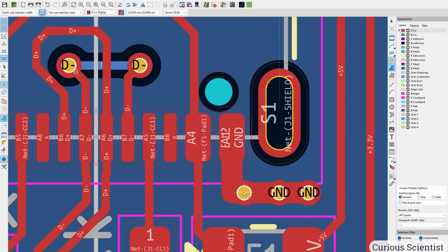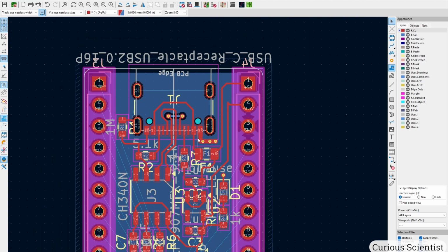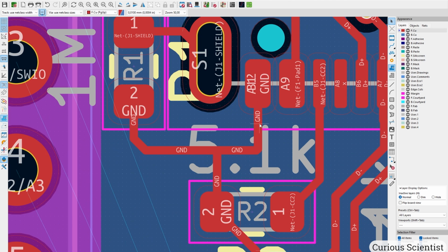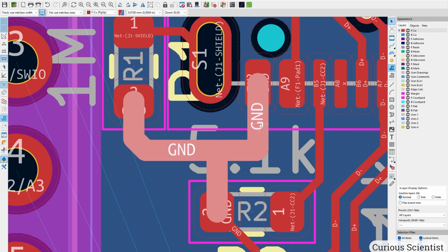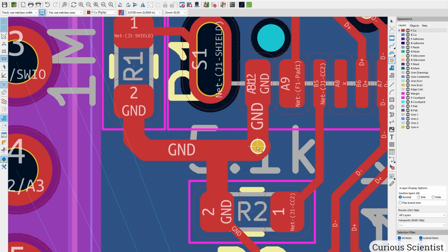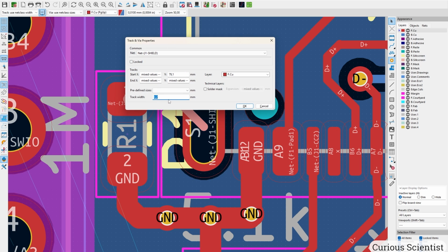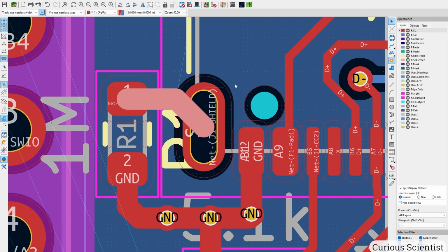So I dig through the board, and now we have a direct connection between the top side input here, which is the ground, and then the bottom of the board. So this is now good, and everything is routed with the ground, so that's really nice. And here I could do the same. So I press U a few times, so everything is selected, press E, 0.5, and again I add a few vias here just to make sure that there is a solid connection between the ground and these traces. This can also be, I press U, press E, 0.5, so it's thick enough.